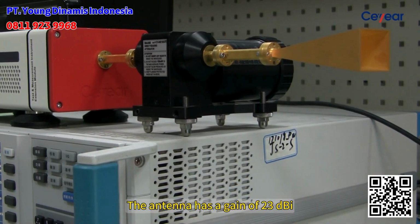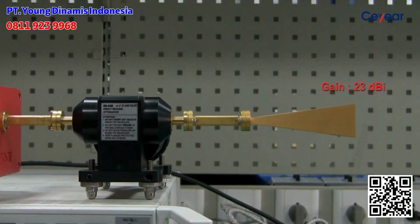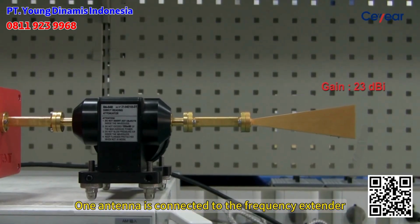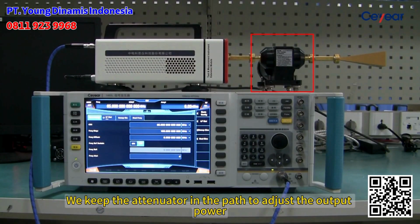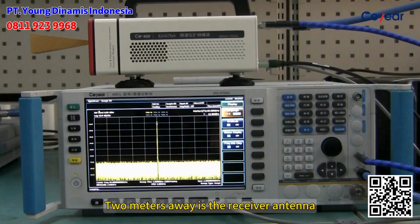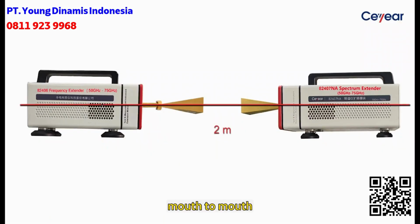The antenna has a gain of 23 dBi. One antenna is connected to the frequency extender. We keep the attenuator in the path to adjust the output power. 2 meters away is a receiver antenna. The two antennas are placed in a straight line, mouth to mouth.